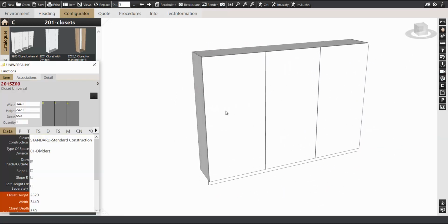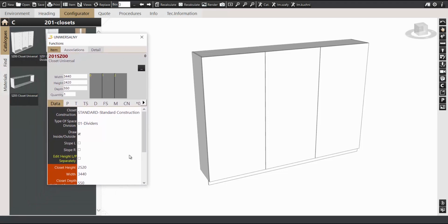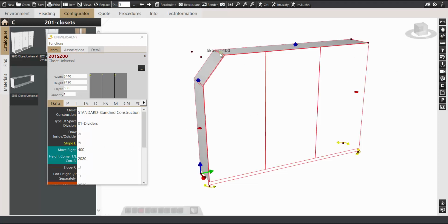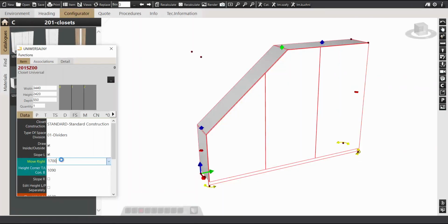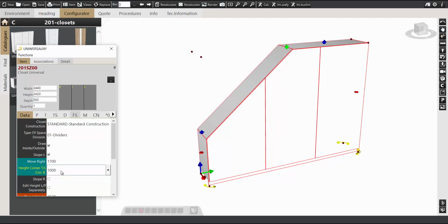After this we now go to the draggers, and on the draggers you find all the possibilities to change slopes or angles. So even when you put it in the standard way, you can change this very easily later, and you can do this in all directions and all dimensions. Naturally, you can change every value, also concretely, by typing in a number like a millimeter. So you can use draggers as well as values in the property tables.